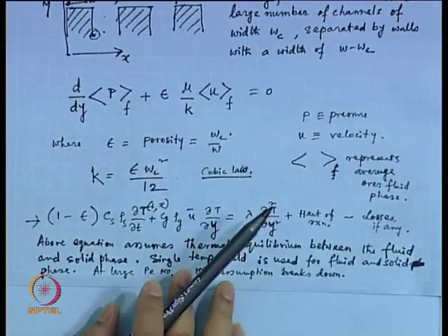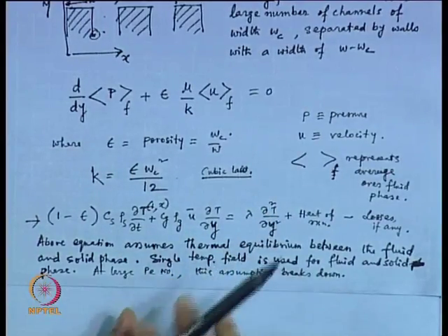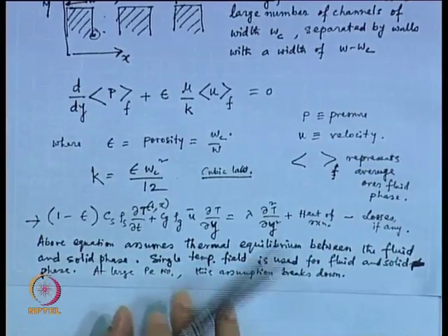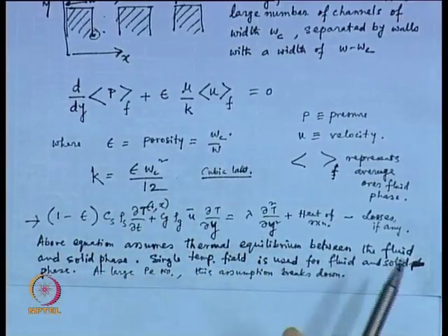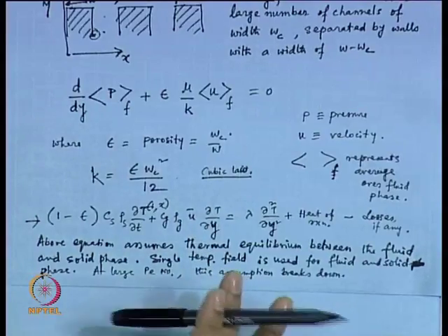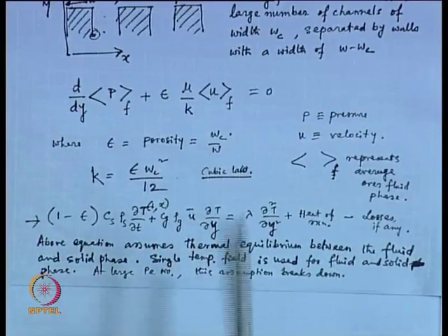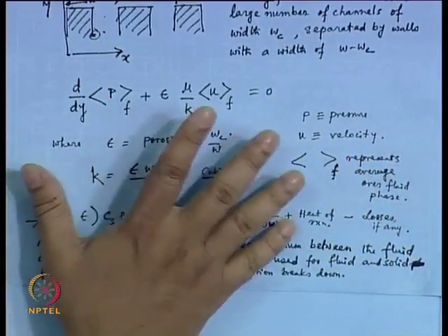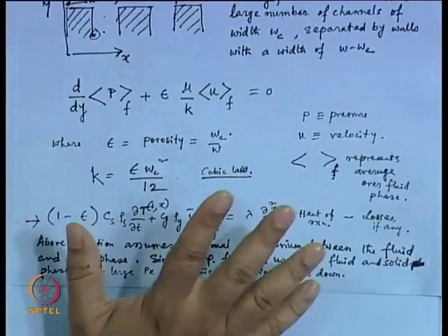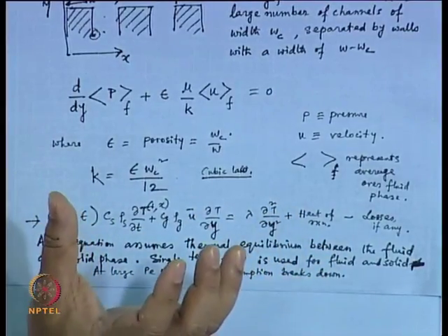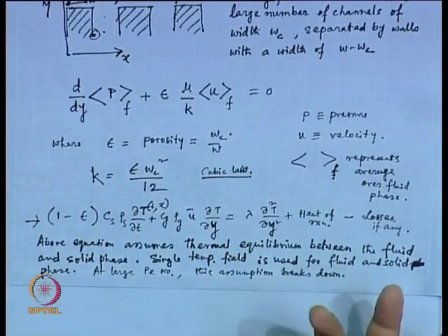However, we are looking for assumptions, because what you may be asked to do is to take up various dimensions of this microstructured reactor. If we take W as this, WC as this, and the material with property CS is this, rho S is this, and things like that, and you have to play with this to come up with the best design for your microstructured reactor, this kind of simplified model would be useful, at least to screen the large bounds you have to play with. If you want to come up with an optimum design, you need a simplified model first to focus on which dimensions or materials to look for, and then you can get to the detailed rigorous CFD model to fine tune the results. So this simplified model is meant for a particular purpose, and by now you must have understood the purpose.